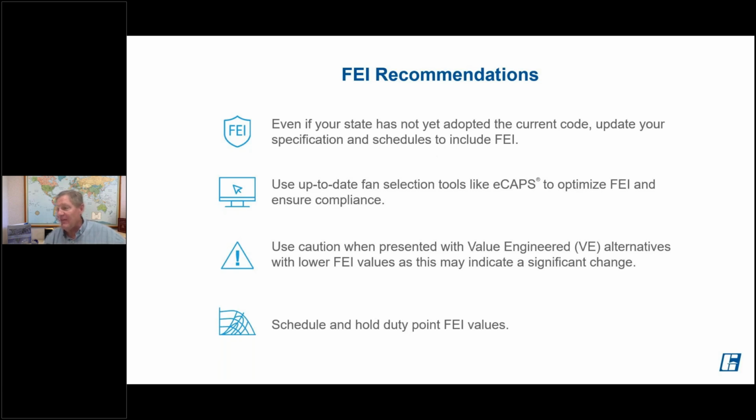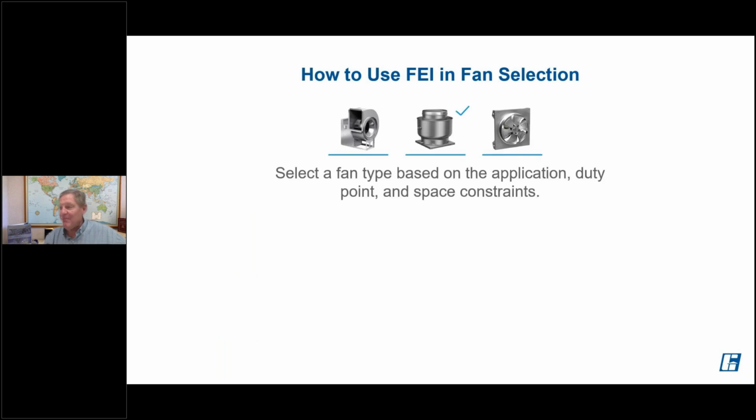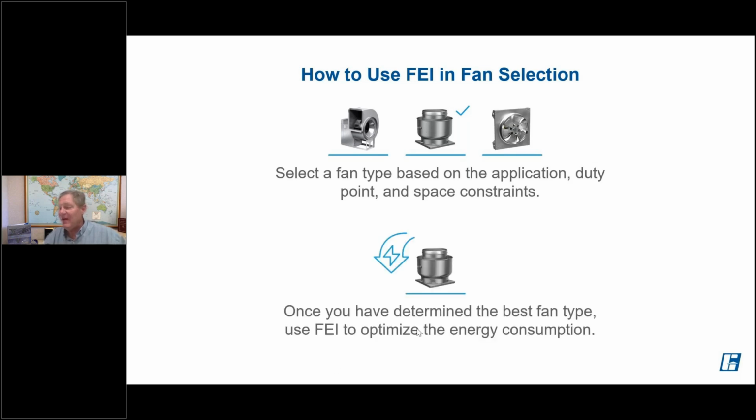Now, having said that, I wouldn't recommend starting your fan selection based on maximizing your FEI or getting the highest FEI level. Start out by selecting your fan based on the application, duty point, space constraints, and all the other things that come into play when making a fan selection. Once you've narrowed that down, then hone in on the FEI and find an FEI that's going to maximize the performance of that fan and optimize energy consumption for that fan.